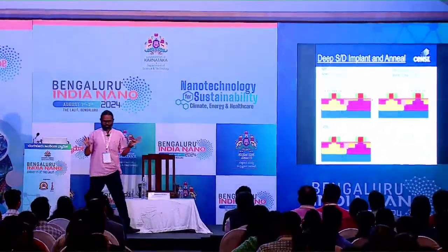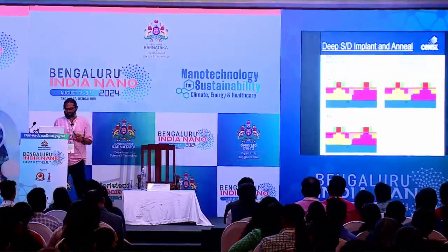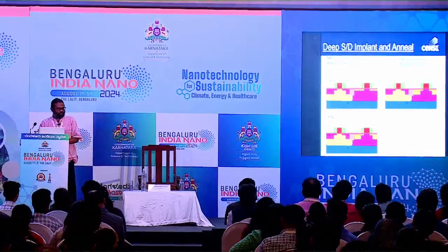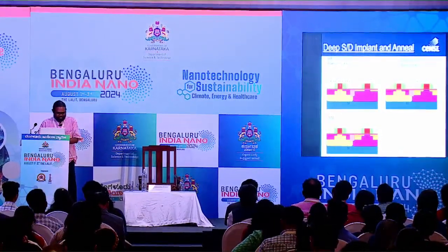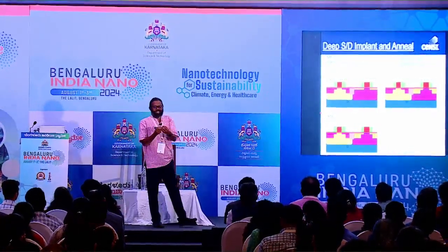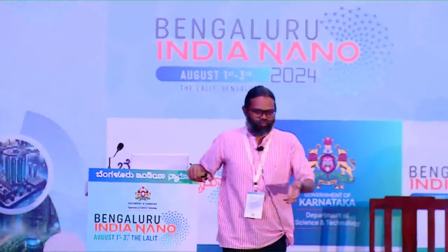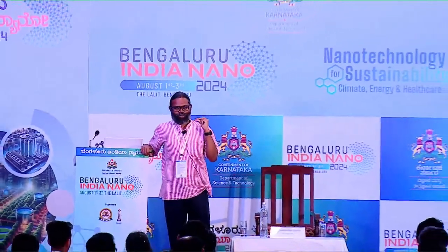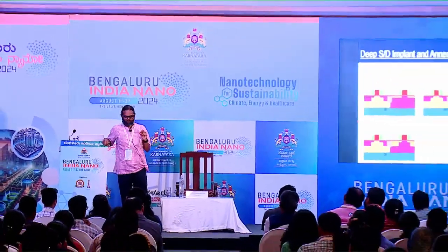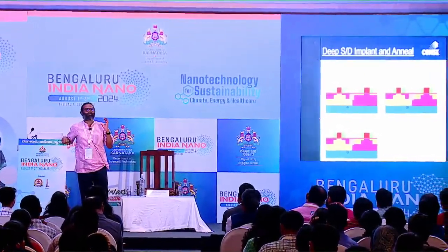So you have doped, right? You have changed the conductivity, and you have a gate that can control the conduction between them, and this is all perfect. So you have a transistor now, right? And before you use it, you have to do some annealing. As I said, there is a catalyst, which is temperature. That RTA means rapid thermal anneal. So you are not going to cook your transistor for a really long period of time. Heat is applied for about 1.5 seconds, okay? And the temperature here is going to be about 1050 degrees.